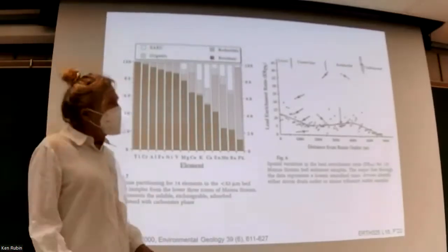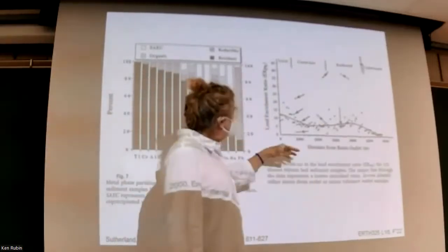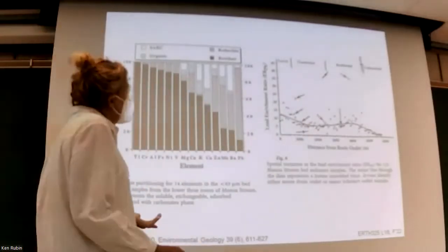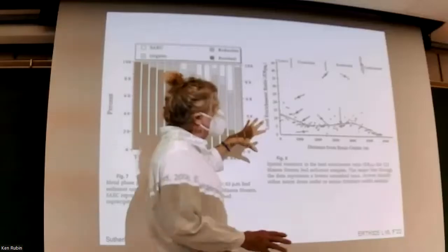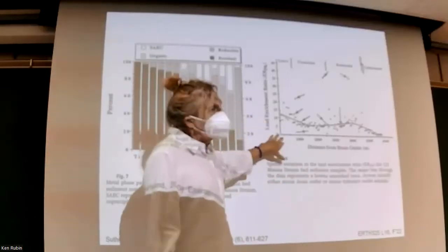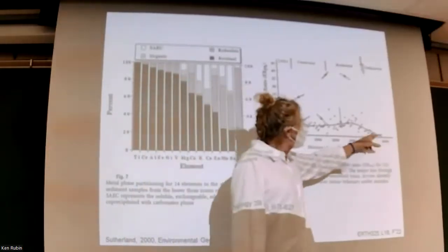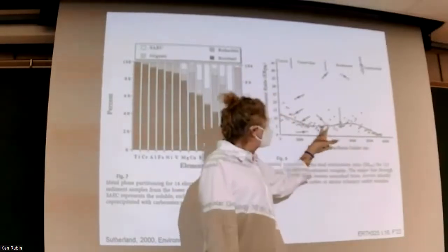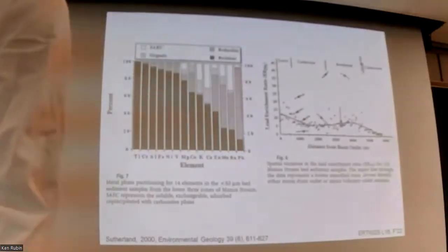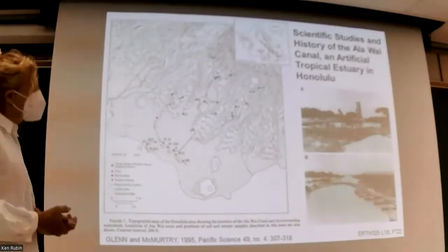And this is basically showing you how lead evolves along the river basin as you flow downstream, how much of it is in the various phases relative to the water. So what you see is that as you go toward the outlet, meaning into Ala Wai Canal or the ocean, there's more, it's accumulating. This water is flowing down the gradient along the 6 kilometer gradient. It's accumulating lead. It's a messy plot, and it varies during the year, right? Storm runoff and all that kind of stuff. But this is the way in which people use these kinds of measurements to understand.